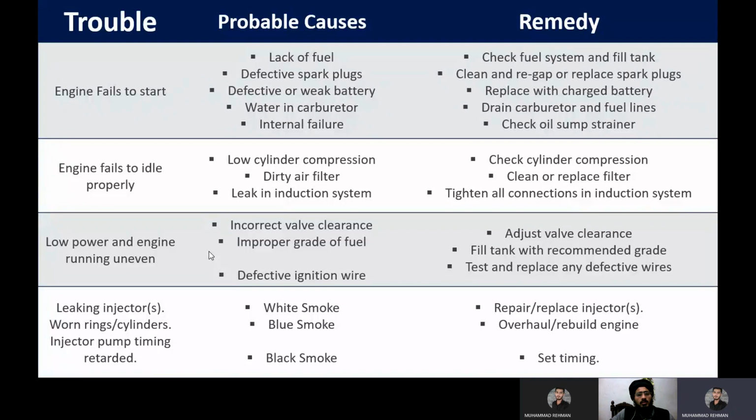If the battery is weak, the engine fails to start. If there is an internal problem, if the piston is jammed or the piston rings are broken, then also the engine fails to start. Or if there is any problem in the intake manifold, so that the required amount of air is not going inside the engine, then the engine also fails to start. A few recommended solutions are written on the right side of your screen.